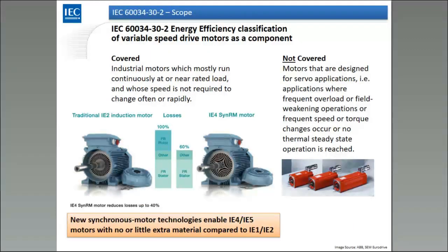Speaking of new motors and comparing high efficiency with low efficiency motors, you sometimes hear some discussions: oh, high efficiency motors are going to be very big, very costly, very heavy, you're going to need a lot of energy to build these motors, and it's not useful to use high efficiency motors because you have to use such a high amount of energy to create them. And of course, depending on the technology, this can be very true. If you, for example, build IE4 induction machines, they are much heavier, much larger than IE2 induction machines. But this is not the end of the story.